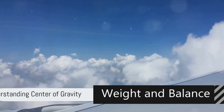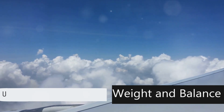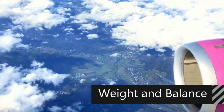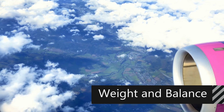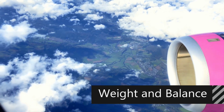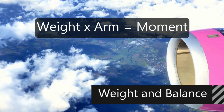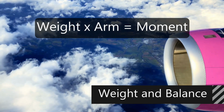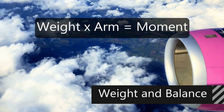The CG is not necessarily a fixed point, its location depends on the distribution of weight in the aircraft. As cargo items are shifted or consumed, there is a change in the location of the center of gravity. Each weight multiplied by its arm results in a moment. Taking this formula into account, we can use two of the three variables to calculate the third.